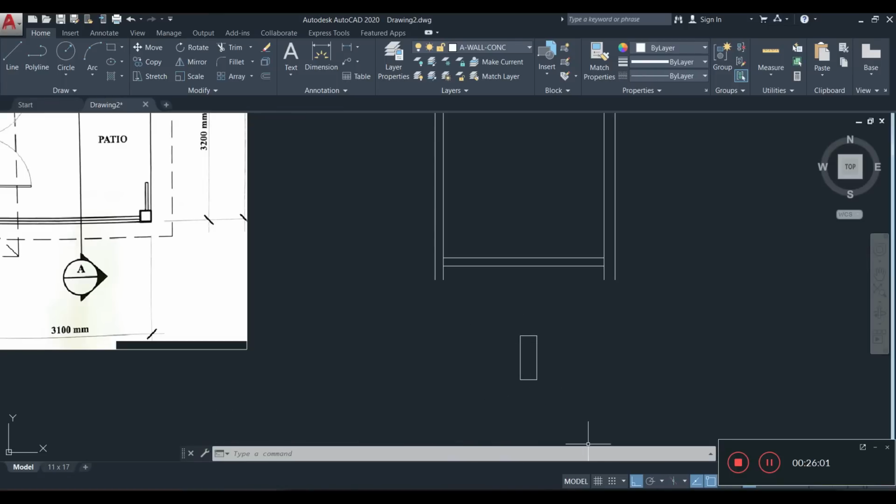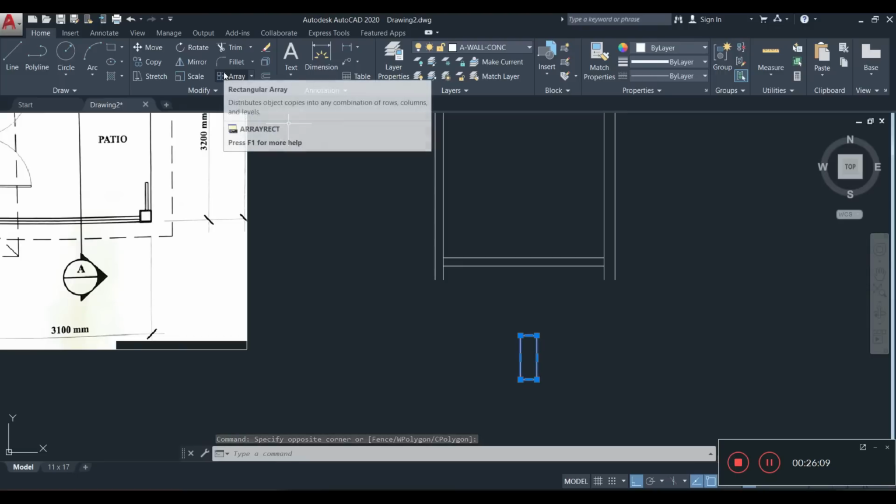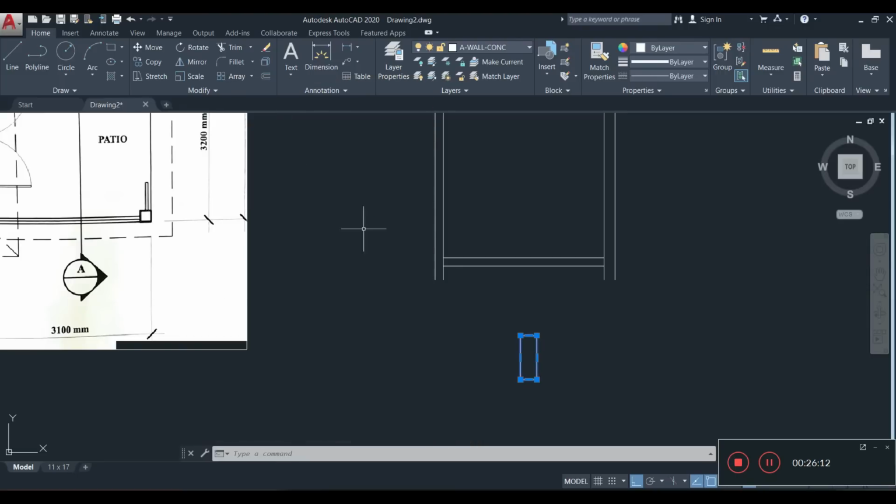I think they have the numbers mixed up, you know, because the first measurement that is referenced always has to do with the width of the building or the width of any object. But in this case, it seems they have flipped it. Alright, so that's one error there. So here's what we're going to do. Let's rotate it. Because since the foundation wall is 200, it only makes sense that the width of the foundation be 800 millimeter. Why? Because the foundation pad is always going to be 3 times the width of whatever object it's supporting. Alright, so on that, let's do our foundation footing portion.